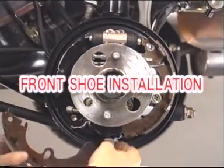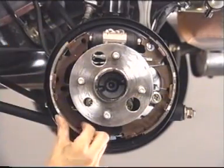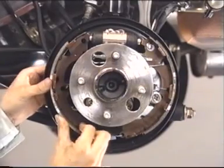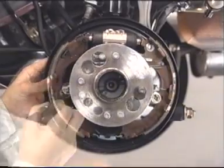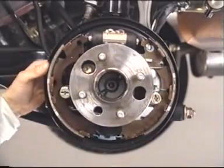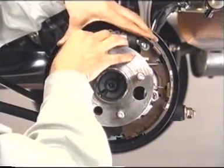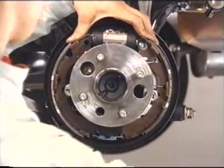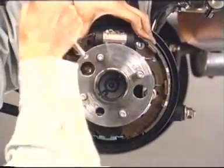Next, install the front shoe. First, assemble the anchor spring between the front and rear shoe. Follow the same procedures as the rear shoe and set one side of the front shoe to the wheel cylinder and the other to the adjuster. Assemble the shoe hold-down spring, two retainers, and the pin using the SST. Connect the return spring using the SST.